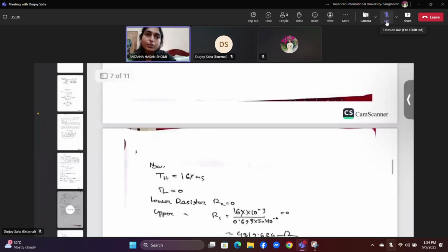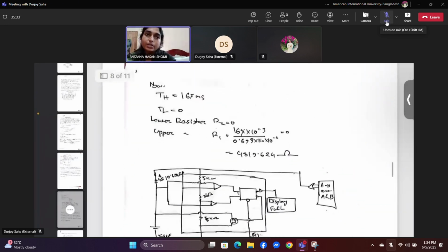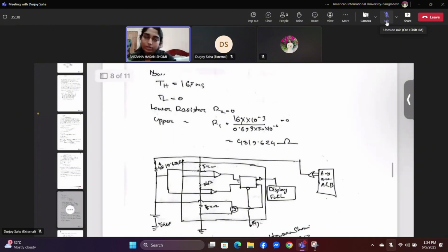In the figure mentioned, we have two values. A represents the value of the resistance connected to the keypad. B represents the value of the resistor connected to the center of our control unit. Since the full display is meant to be continuous and not blinking, we have decided to use another timer in astable mode to manage the display of other messages like space available. To ensure smooth and reliable operation, we have designed the system by adjusting the duty cycle. This way, the output signal can be tailored as needed.